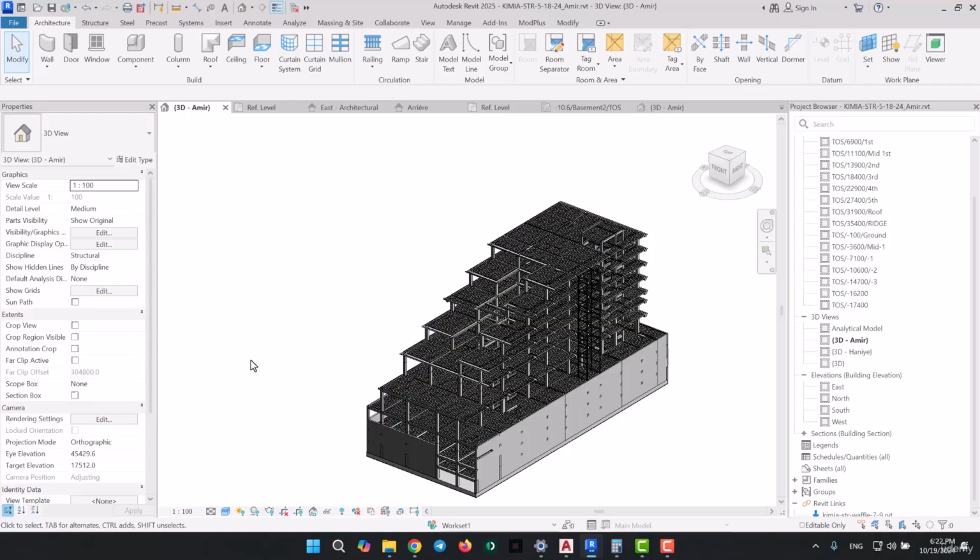And another thing is that in order to speed up our process, we opened a generic model line-based family, loaded both of the waffles in it, then we assigned parameters to both of their visibilities, then we arrayed them, and after that we also added formulas to those parameters to make it easier to switch between the waffle shapes whenever we need, and eventually change their types. And finally, we were able to place them.